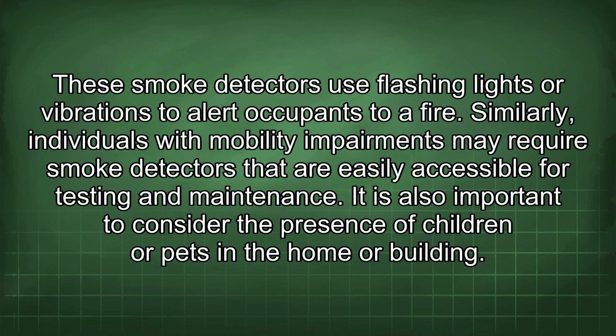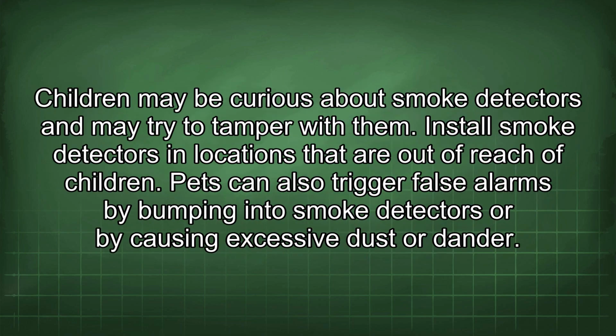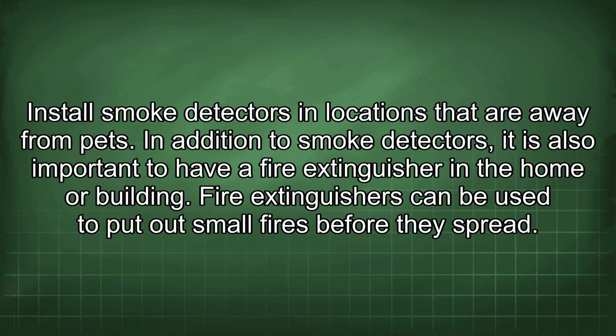It is also important to consider the presence of children or pets in the home or building. Children may be curious about smoke detectors and may try to tamper with them. Install smoke detectors in locations that are out of reach of children. Pets can also trigger false alarms by bumping into smoke detectors or by causing excessive dust or dander. Install smoke detectors in locations that are away from pets.